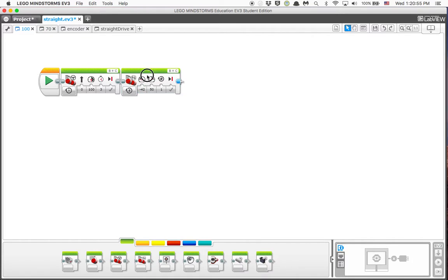Now, you can test this out to see how well your robot drives straight. And as I mentioned at the beginning, the idea of feedback control systems, this is a whole other concept. And then actually just driving straight. Robots can't drive straight. You need some sort of feedback system because things are inconsistent. Things are not perfect. Two motors are not exactly the same, and then two pieces of your terrain, your road, are not exactly the same.